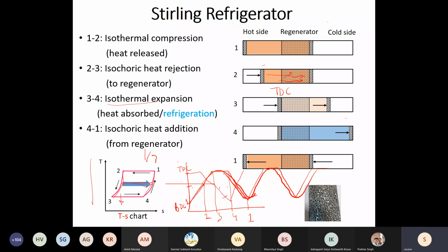when it comes back, so the idea behind this is when this gas now passes back through this media and goes to this volume, that is the 4 to 1 process, the gas will flow through this porous media and the cold gas will become warm. That is why the porous media is there. So it is just providing the M into Cp to store. So it is acting as a reservoir, it stores and then releases the same heat.